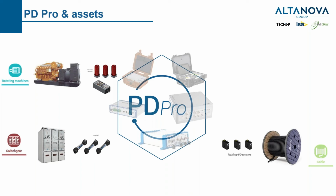Normally in this case, we can differentiate between high frequency current transformer, or we have other sensors like flexible magnetic coupler. We can have embedded sensors in the high voltage cable. We can have HFCT around the cable. So it will be interesting also to store this data into the PD Pro and create our own DB with all the different testing solutions.